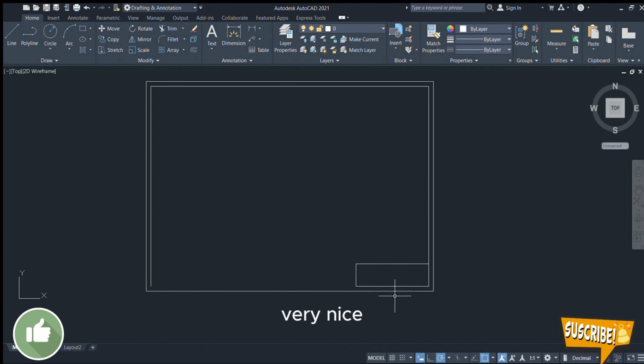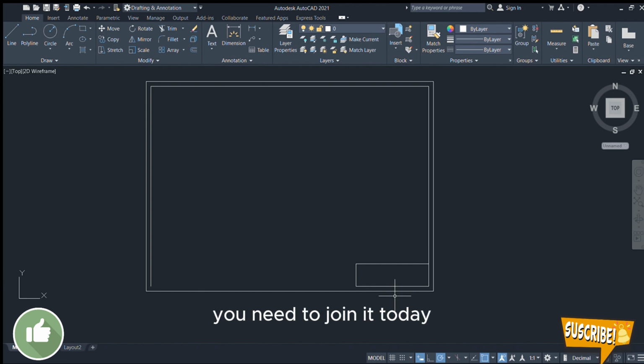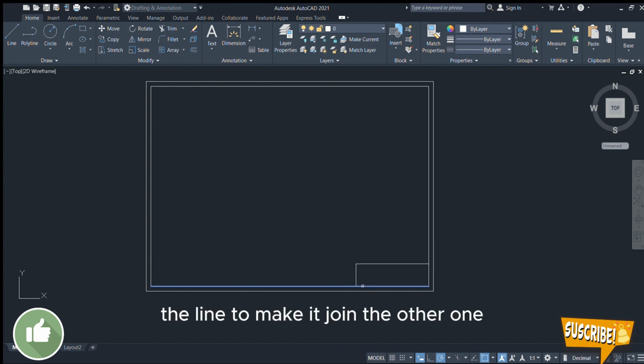Okay, very nice. Like I said earlier, after creating your title block, you need to join the down line back to where it was. You need to join it to the bottom left corner of the inner borderline. By doing that, you type extend or EX, and you enter, and then you click on the line to make it join the other one.